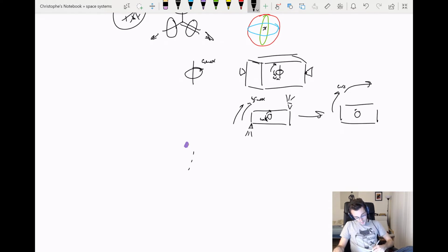And their orbit was really eccentric, so they'd get really close to the sun and really far away. So their velocity right here is stupidly huge. I'm going to put this in a giant V, right? Which means that if they want to look at the sun, they've got to shift their attitude really fast. They've got to have a really fast angular velocity at that point in their orbit. So what they would do is use their thruster systems to actively desaturate their reaction wheels every orbit, because they wanted fine control to be able to look at different spots on the sun, but they also need to have really high angular velocities.